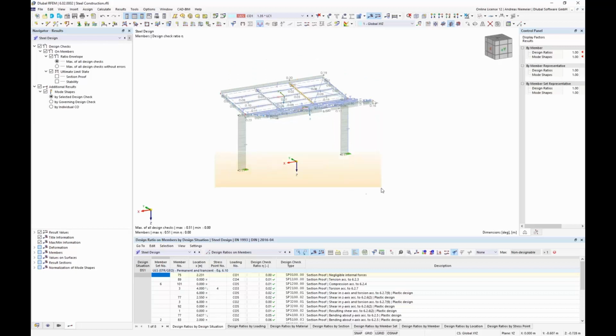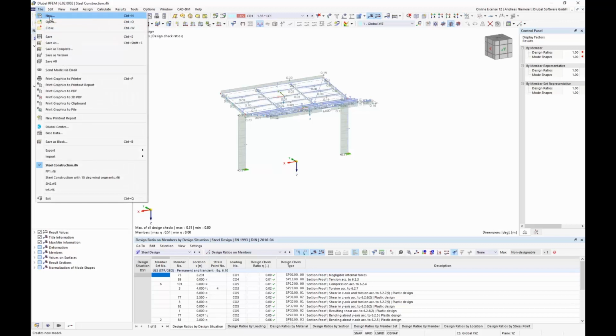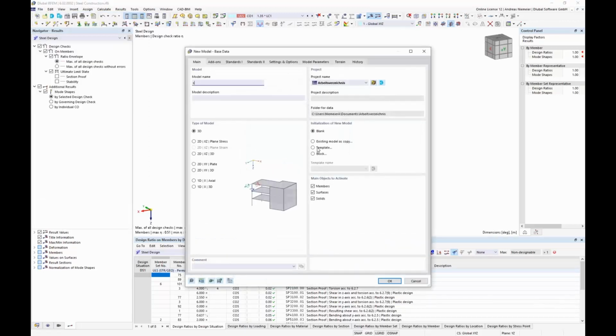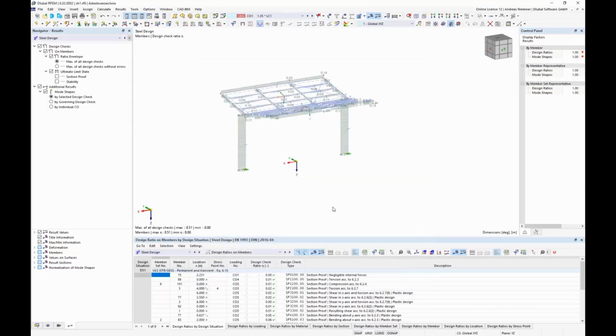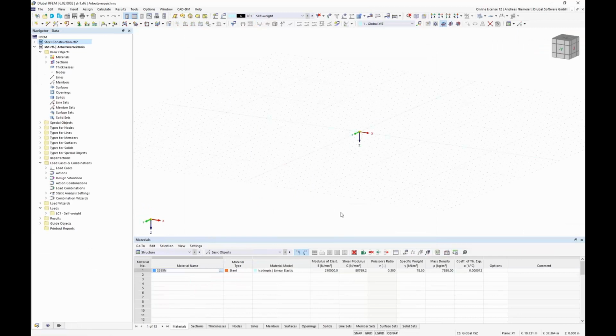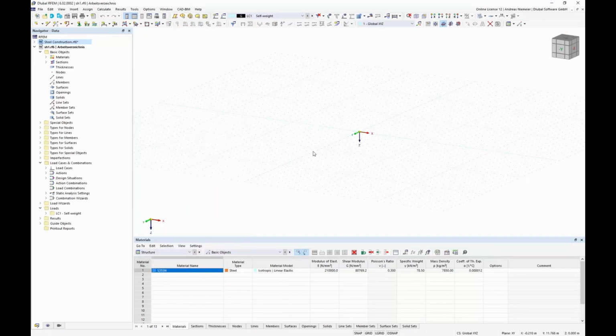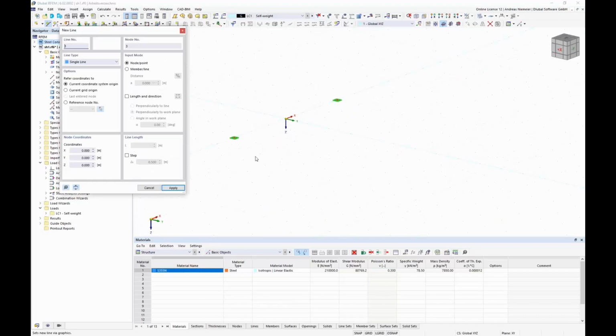So let's copy these 2 points here and go into a new model, shading 1, and model a shading, how it looks like. These 2 points, I only have so that I know how big the shading should be. And let's draw a plane view of this shading.